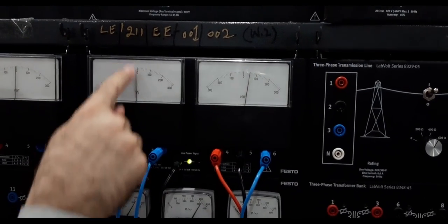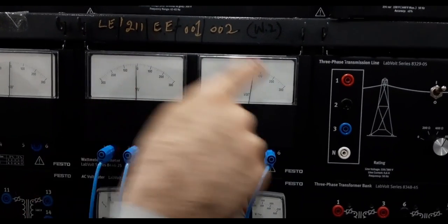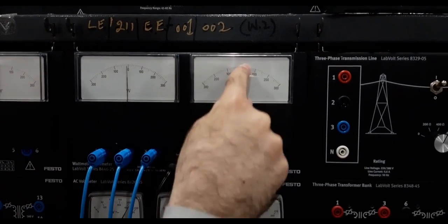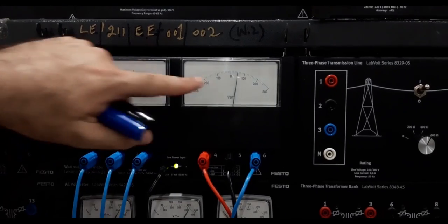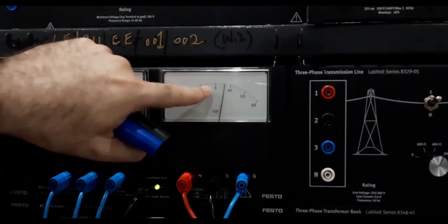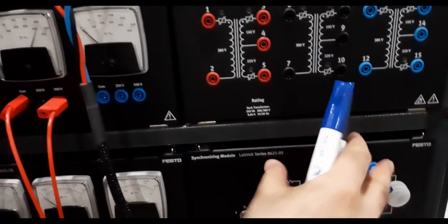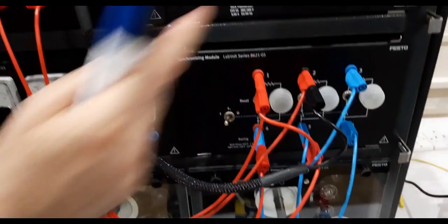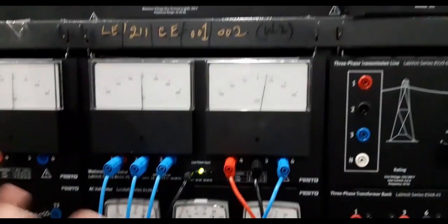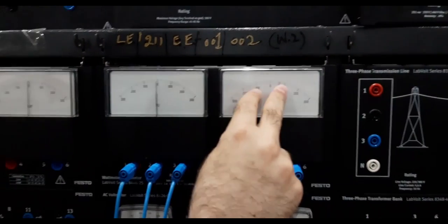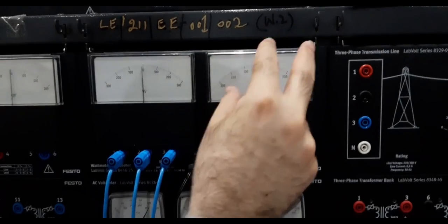If it moves in that direction, it indicates consumption. There is no change in the active power. You see, if I change the field current, there is no change in the active power, only the reactive power changes. And if I further reduce it, one can see the consumption increases because the terminal voltage is fixed. As it is connected now to the system, the induced EMF reduces, and the more it reduces, the more will be the reactive power consumption. So this is under excited case.